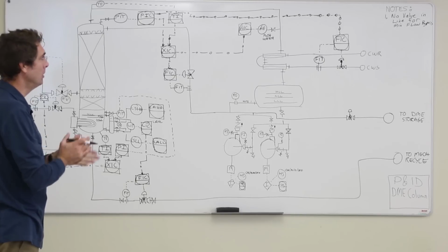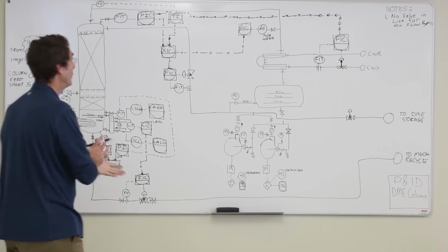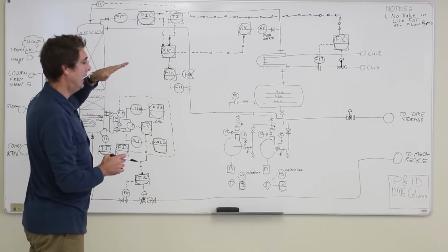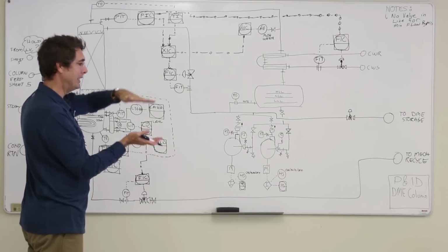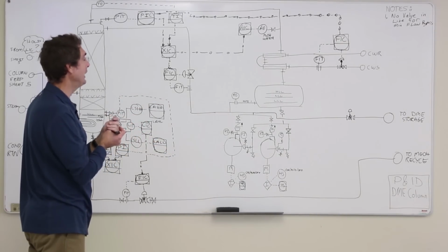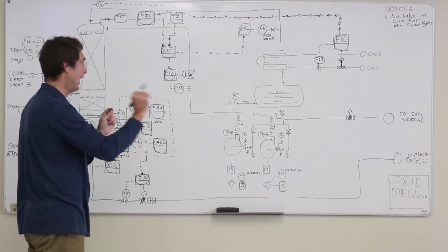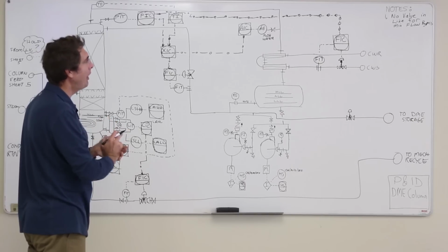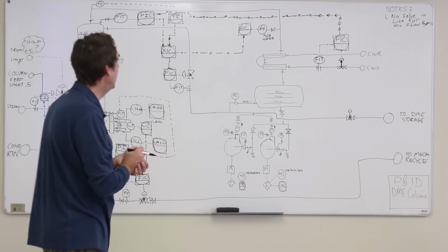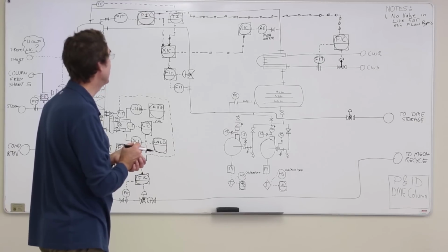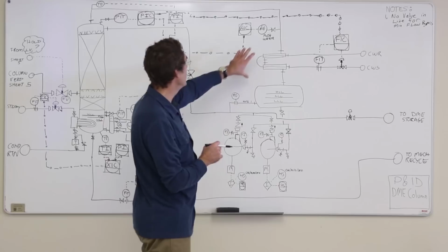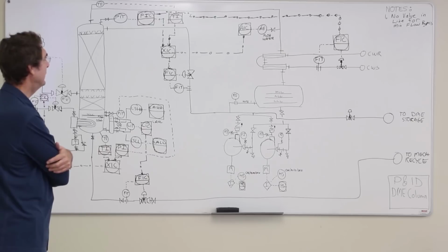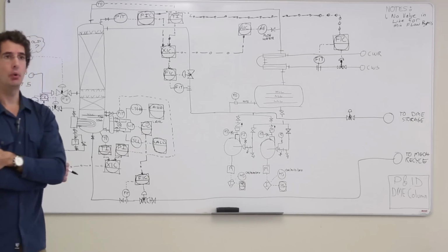The recommendation, a little bit of an old recommendation but still probably quite relevant, is to keep the pressure between bounds, but not try to hold a really accurate pressure 100% of the time, at a particular value. So kind of have loose pressure control. I'm not sure whether that's the right way to do it with this particular tower, because we're trying to get down to such low concentrations of methanol in water. If we let the pressure float around very much, I'm not sure how good that's going to be for our